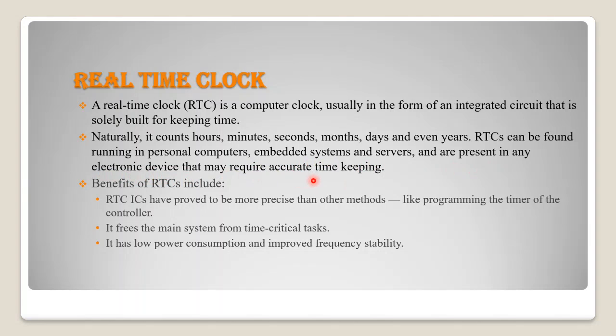may require accurate timekeeping. Benefits of RTCs include: RTC ICs are more precise than other methods, like programming the timer of the controller. It frees the main system from time-critical tasks. It has low power consumption and improved frequency stability.